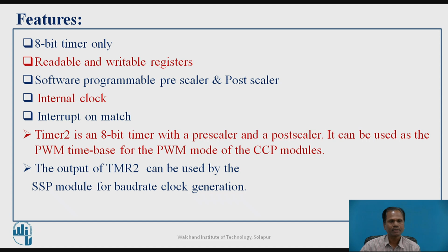It internally contains some readable and writable registers like timer 2 register and a period register. So timer 2 module has a software programmable prescaler and postscaler. Internally it contains a prescaler on the input side and postscaler at the output side, which are software programmable.